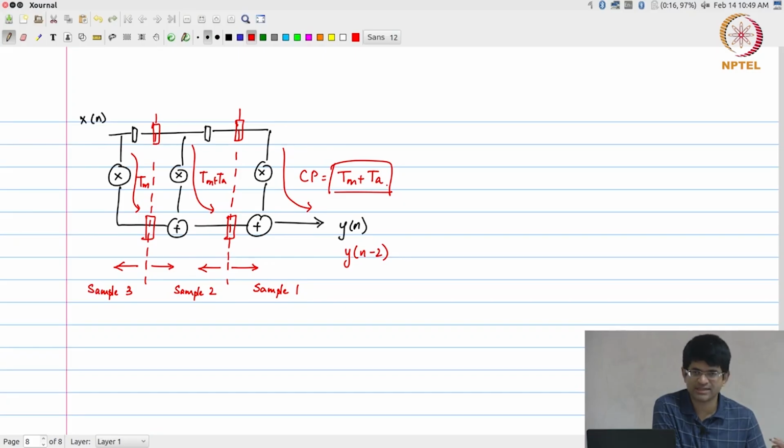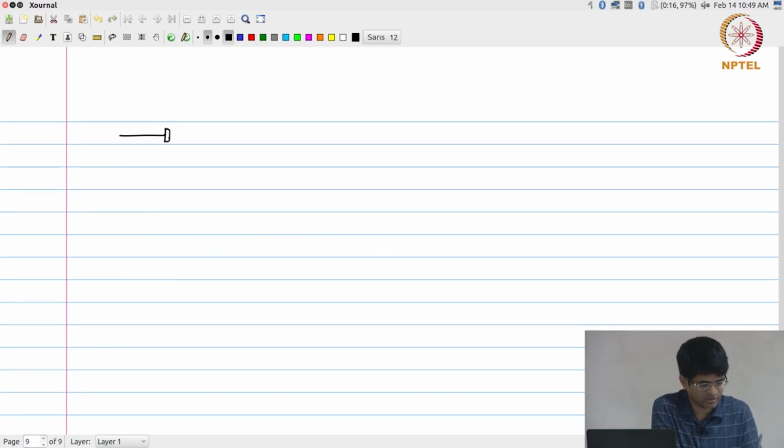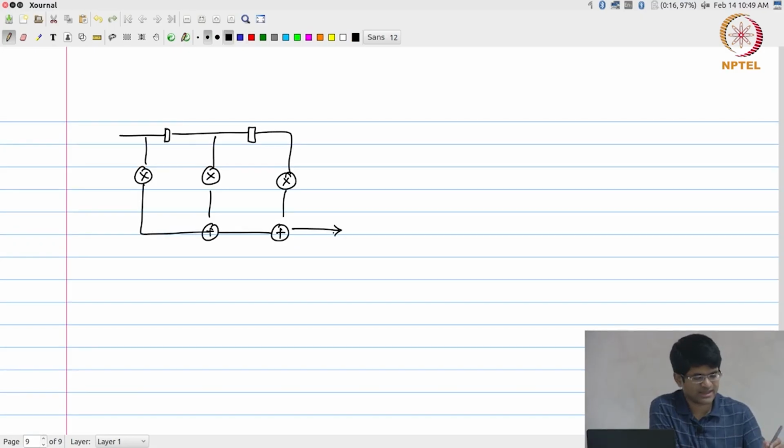Part of the reason for that is I chose the wrong lines for doing my pipeline separation. Let us see if I could have done it slightly differently. That is also very easy actually to do. All that it is saying is, why not choose this as my division. This whole notion of left and right and what is happening before and after are just some physical constructs that we are using to visualize. All that really matters is logically what is happening before what.